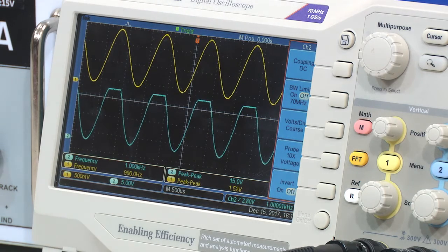That means that from this kind of experiment we can easily find what is the input voltage range and what is the output voltage range. So, this is an extremely simple experiment you can perform within 5 minutes of your time to understand the input and output voltage range of the integrated circuit, that is your operational amplifier, and also remember that it depends on the bias voltage that you are applying, alright.